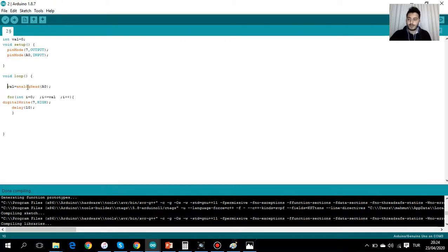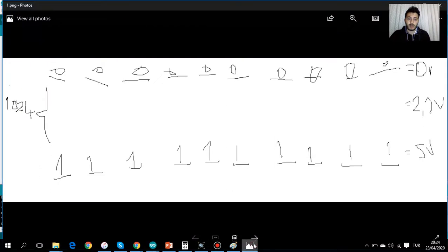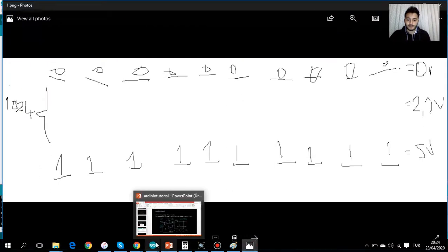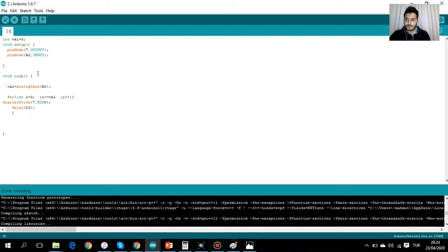I want to talk to you a little bit more about it. I read my value, the voltage from the analog read, and I assigned it into value. Now my value holds my voltage in decimal, which I already told you how we convert.